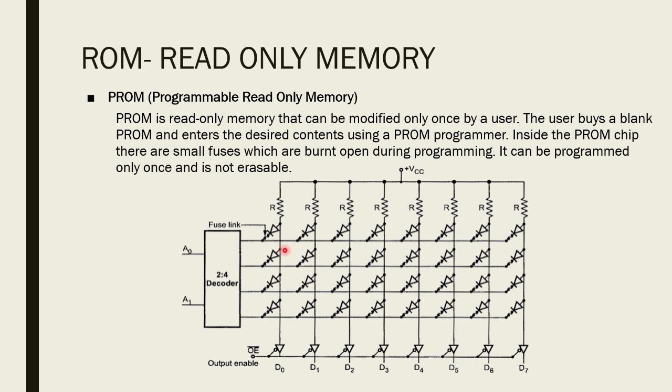The fuses in the PROM are blown by application of high voltage pulses to the device through a special pin. A blown fuse defines a binary 0 state and a fuse which is intact gives a binary 1 state. All the procedures for programming ROMs are hardware procedures. Even though the word programming is used, once programmed, a fixed pattern is permanent and it cannot be altered.